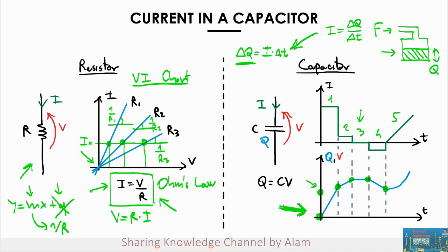And now, if we had to represent the evolution of the charge from that point, it would be very simple to calculate, because as we said before, we are simply computing period per period the extra charge that is added to the capacitor. So in this case, if we start from this point, the resulting charge will be like this. So it will just be exactly the same graph, but it will just be shifted up by the amount of the initial charge.